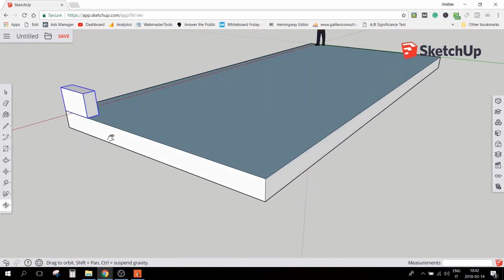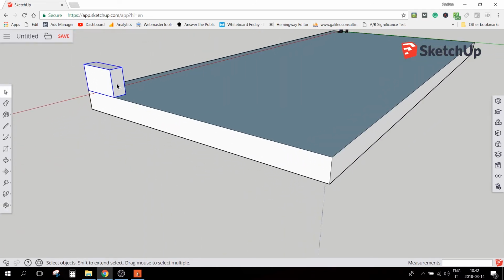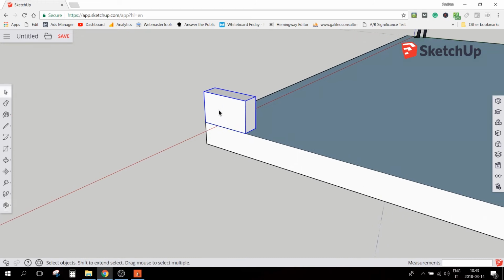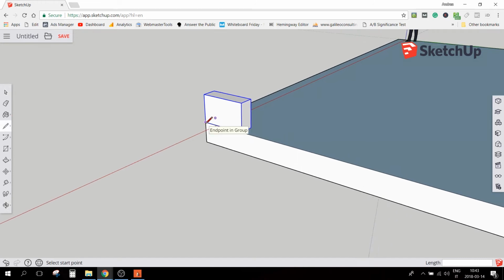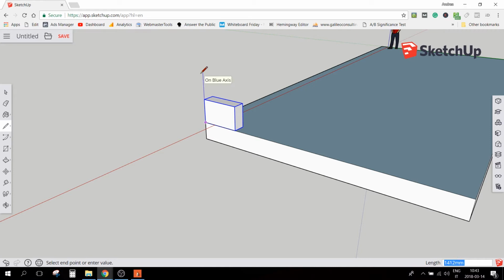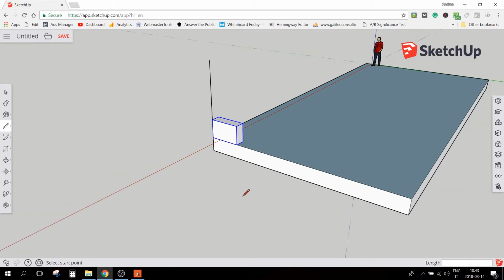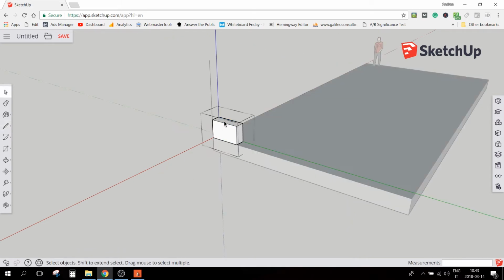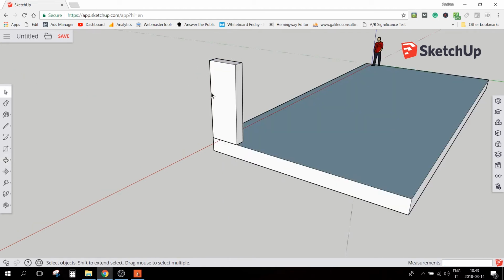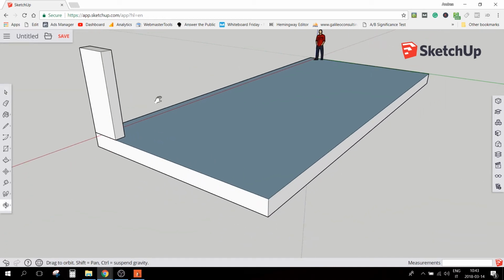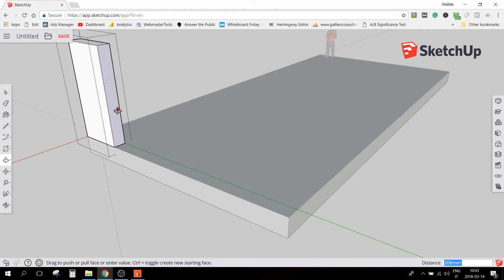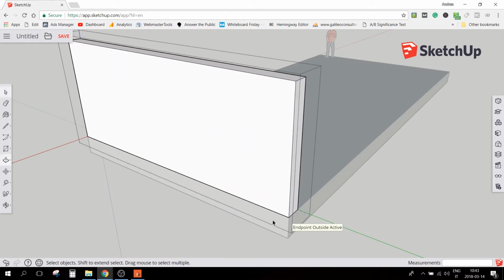You see, there are two separate objects, and so what I can do is now I take a reference line. I could have pulled the entire thing, but I want to make it 2700. Okay, so I use this reference line and I double click, P, pull this thing up to the line. Yes, now I delete the line. Remember, the line was outside the object. And now I will click this thing, double click, and extend it here. So this is my first wall.